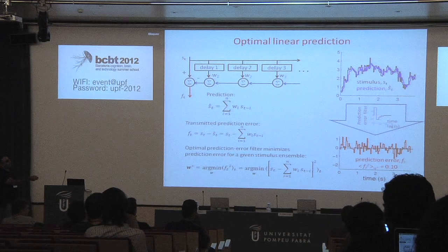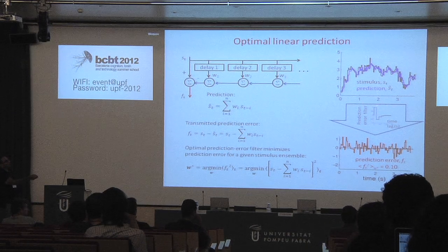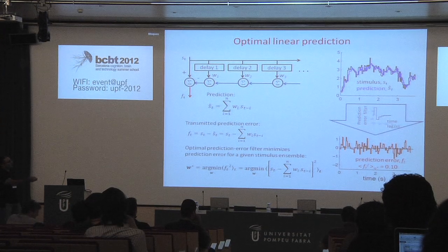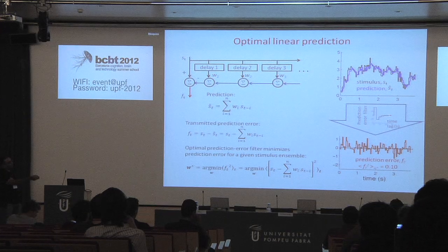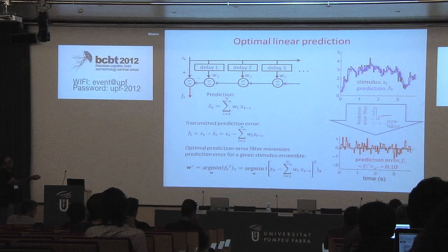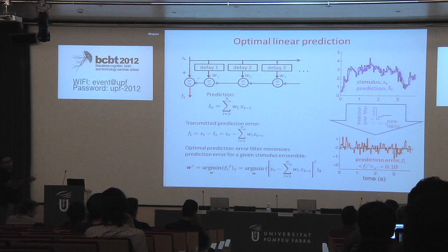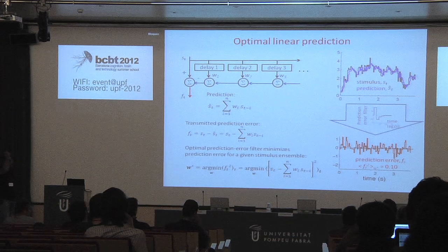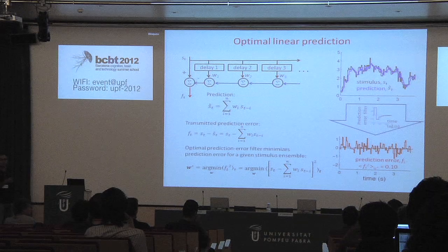As you can see, it still has a coefficient of 1 corresponding to the current value of the signal. This is this line. But then the coefficients for the past value of the signals are much less than 1. And actually, all of them summed together are also much less than 1. But the prediction now depends not only on the previous value of the signal, but also some of the older values. And the reason you would do that is if there is some noise in the signal and you want to come up with a better prediction by averaging it out.